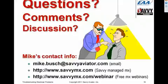I've followed a bunch of these incidents. Some of them have occurred at pattern altitude, some have occurred up at the flight levels, some have occurred with extremely high time CFIs at the controls, and in not one instance did the pilot have the presence of mind to try to turn off the bad magneto. Had he turned off the bad magneto, the engine would run perfectly fine on the good magneto, and it wouldn't be an emergency.